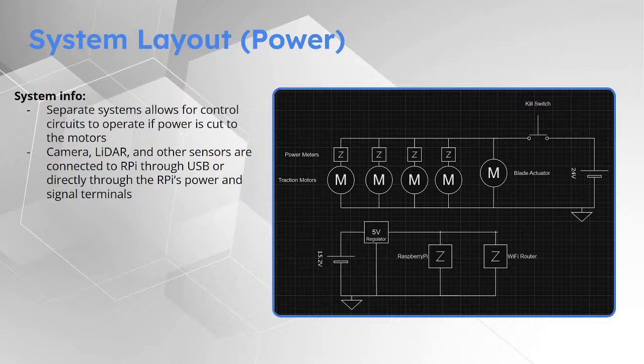One thing we have looked at that I would appreciate some input on is potential noise between the 5 volt and the 24 volt system. Now we are using brushless DC motors this year as opposed to stepper motors. Are you not using separate batteries? We are using a separate battery for the logic. However, they do still need to be grounded together for the RS-485 signals to communicate reliably. Not if you isolate them.